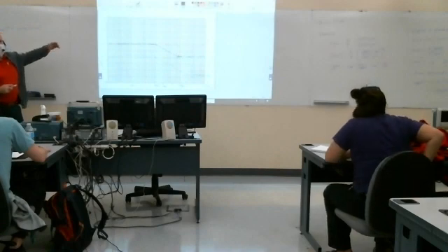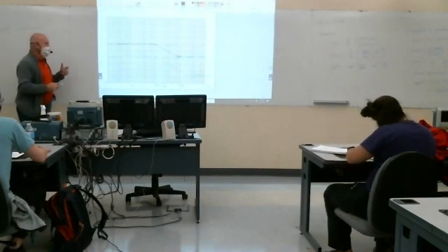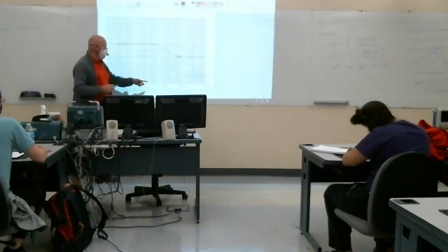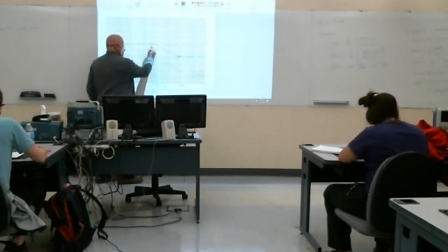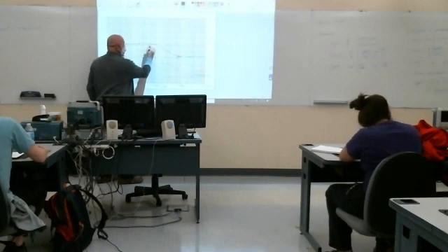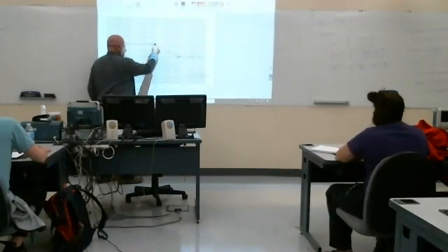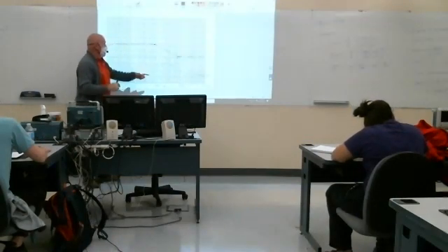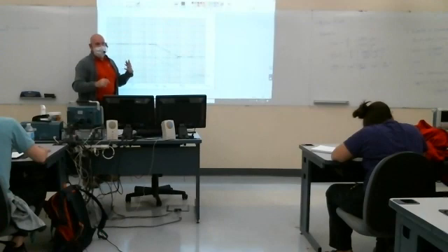We've got higher gain at the lower frequencies, and this appears to pass through frequencies up to about 1,000. The true response would be off by 3 dB here. This 1,000 is actually the 3 dB frequency, or the corner frequency. It would be the cutoff frequency of this filter.